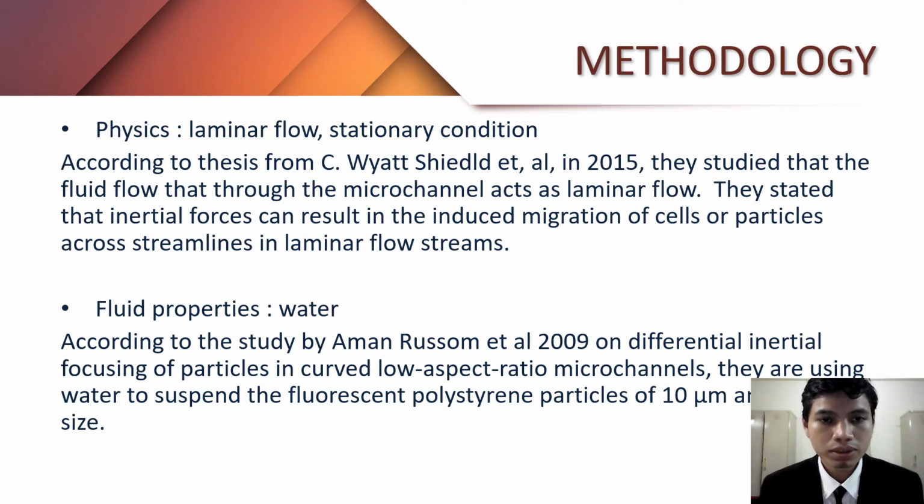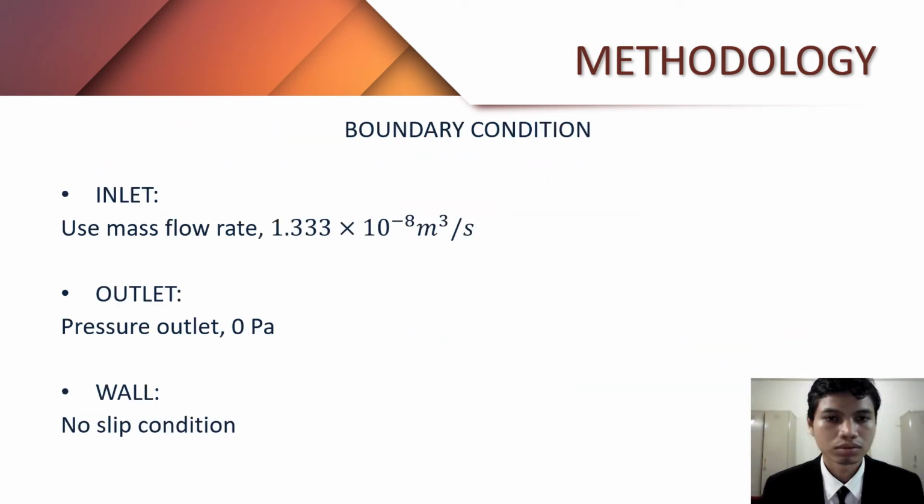Next, the fluid property is water. According to the study by Aman Razan in 2009 on the differential inertial focusing of particles in curved low aspect ratio microchannels, they used water to suspend the fluorescent polystyrene particles of 10 micrometer and 20 micrometer size. The boundary condition that I've used is as stated here.